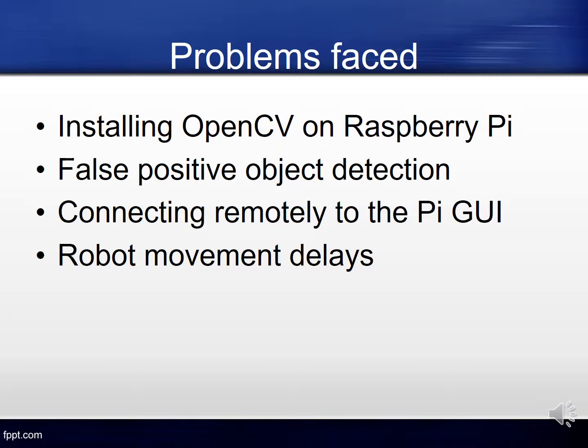To eliminate this, we have constrained the radius of the detected object so that we can detect only the predefined object. The camera detects multiple false positives if the background is not smooth. Initially, we faced a lot of problems because false positives led the robot astray. But once we identified the problem and debugged the code, the robot received clear directives to move.